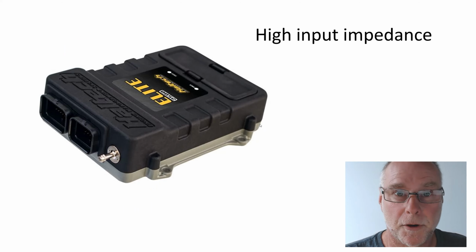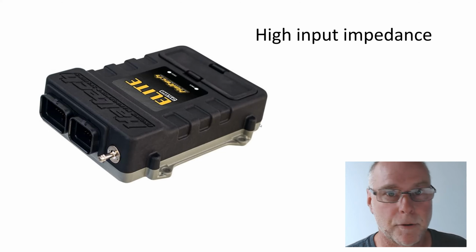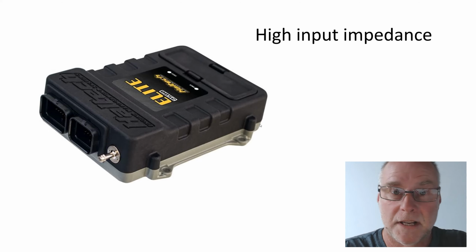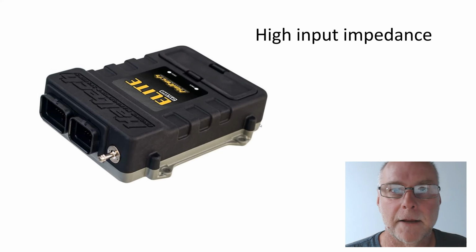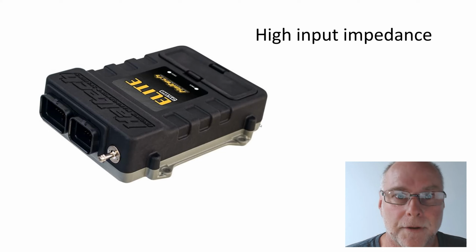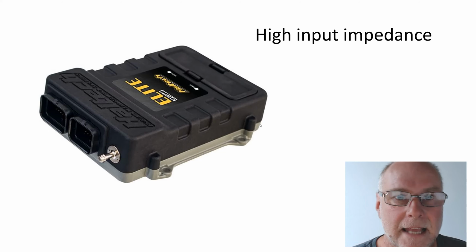So if we wanted to monitor battery voltage, we could just connect 12 volts straight to one of its analog inputs. If we wanted to monitor the voltage coming from another signal, another sensor, we could just connect it straight to it. Very little current flows in the circuit because it's got high input impedance. I remember reading a few years ago someone saying, well, you just couldn't connect the input to the battery, would you? It would destroy it. Don't you have to put a resistor in? The resistor is built inside the unit. It acts as if it has a high resistance because of the way in which it's sensing that signal.